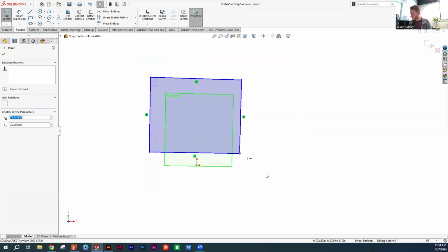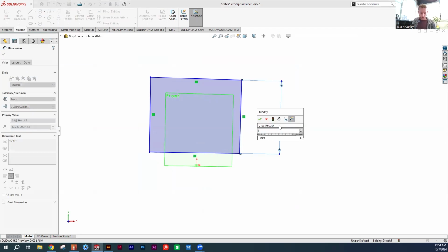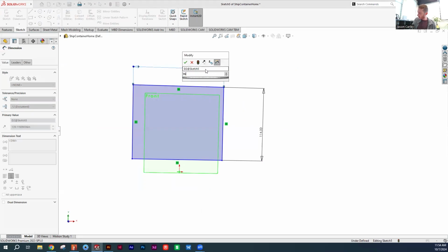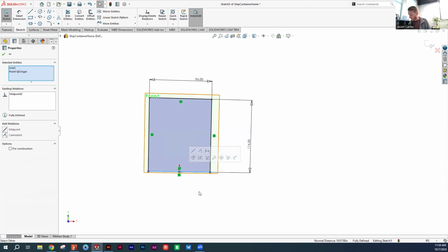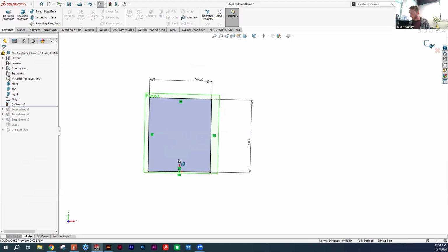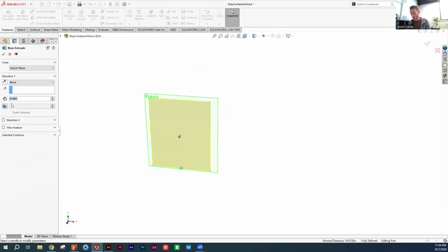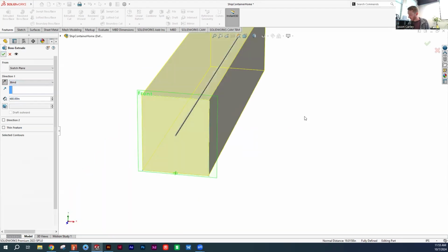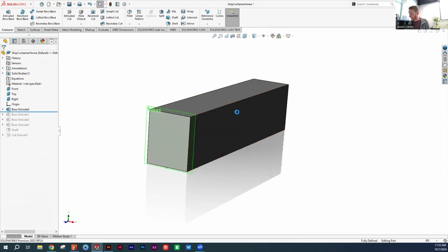use dimensions in here to say, okay, well, I want this to be 114 by 96. Make the origin midpoint to center that sketch around in the front view, extrude that out to be 40 feet. I'll use the apostrophe symbol for that. I want it to go that way. All right, cool. Three-dimensional object for the first shipping container.